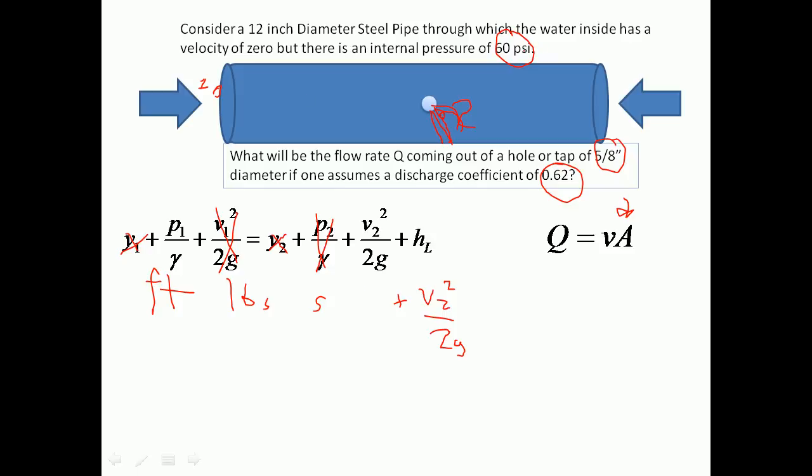All right, so 60 psi, how do you convert it? If there's not a datum shift, you can convert it by any number of ways, but many of you should be able to do 60 pounds per square inch, multiplied by 144 square inches over 1 square foot, to get pounds per square foot. Or, if you need to, use the pressure converter in your calculator.